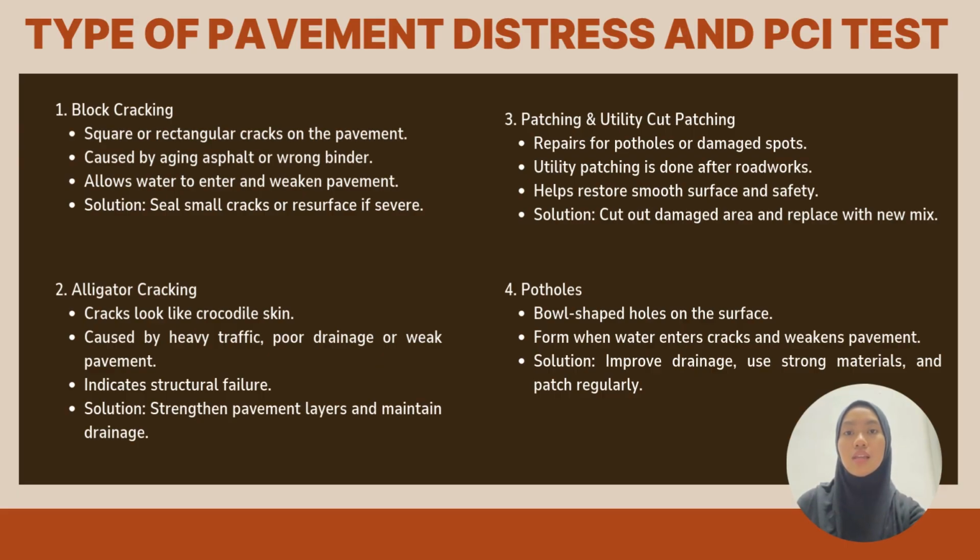So next is alligator cracking. This crack looks like crocodile skin. It is caused by heavy load or poor drainage, and it shows pavement failure. So we fix it by adding a strong layer and improving the drainage.